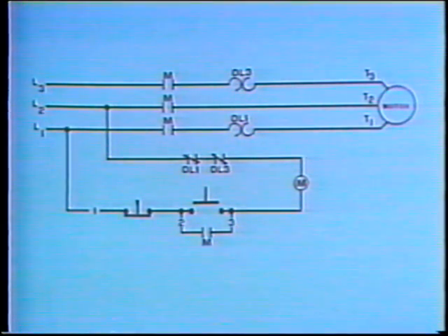From the schematic, the electrician determines the normal operation of the motor controller. Normally, when this controller's start button is pushed, a complete circuit is made from the electrical power supply through the operating coil of the magnetic contactor. The operating coil is energized and closes its main contacts in the motor circuit and the maintaining contact in the control circuit. Current flows from the electrical power source through the motor so that the motor starts operating.